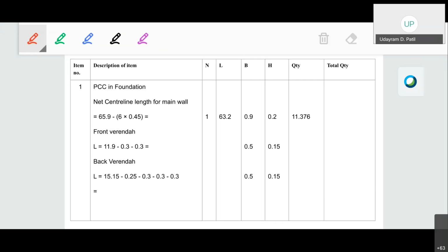Always remember, in case of the centerline length, the number will always be one. ओके. जेव्हा नंबर तुम्ही लिहिणार, फर्स्ट कॉलम, थर्ड कॉलम ऑफ द मेजरमेंट शीट, द नंबर्स विल बी ऑलवेज वन. ओके, हे लक्षात ठेवा. सेंटर लाईन मध्ये कधी वनच असेल, इथं कधी डबल नको लिहित त्याला. ओके.